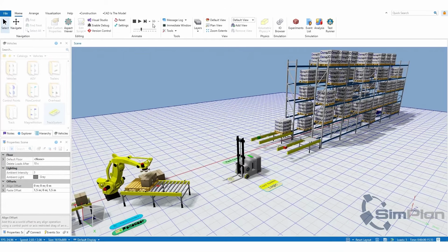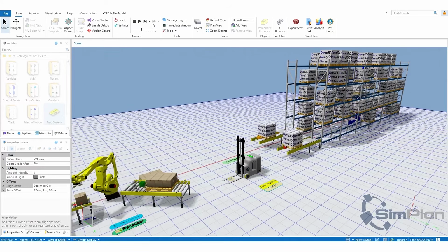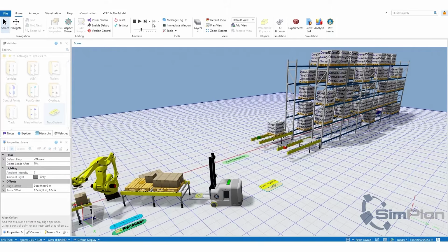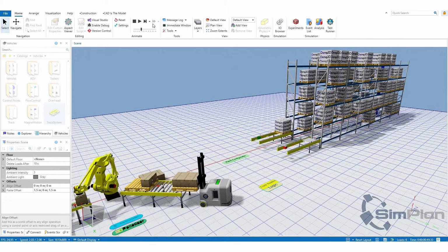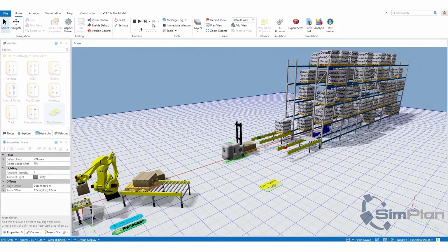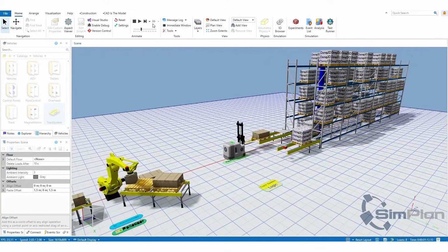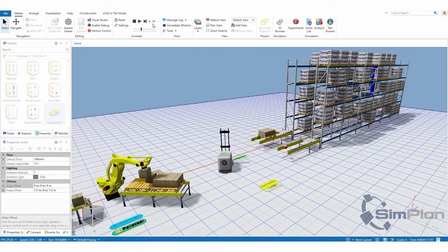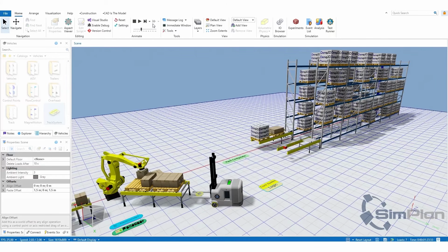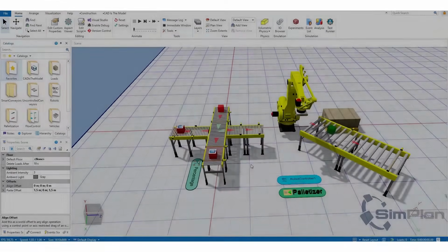When using Emulate3D models for process simulations, the process speed can be increased. The modules from the data collection library can be used to log result data such as throughputs and utilization rates. These are then output numerically or in diagram form. The automated determination of optimal solutions is possible through the use of meta-heuristics. For training algorithms, Emulate3D can be run containerized in the cloud, enabling mass runs. Many of the ready-made modules can be used for both process simulation and virtual commissioning.